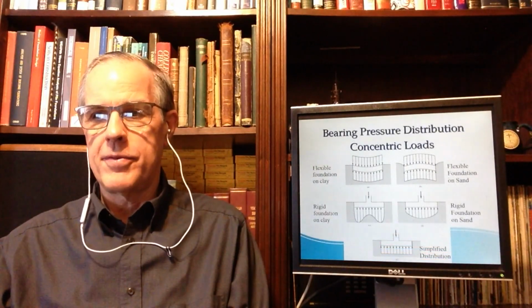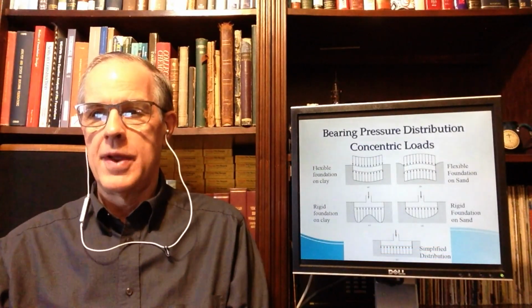We assume for mat foundations they're more towards the flexible end. And that's the big difference from a design standpoint between the two of them. There are other things. You don't see much bearing capacity failure with mat foundations. But it's probably better to move to the next slide to get to the bottom of why this is important.